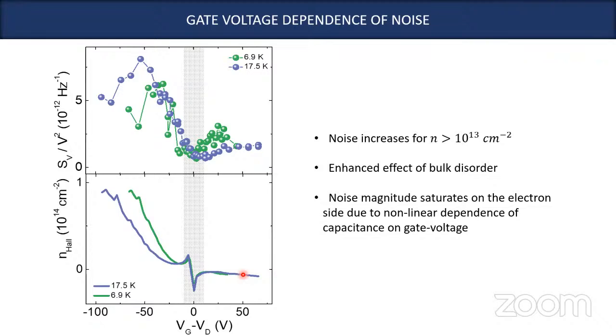You have a gray line, a broad line. That gray line corresponds to close to the Dirac point, where you have zero number density. So these are the charge neutrality points. Yes, because it is plotted as Vg minus Vd instead of Vg, so at Vg minus Vd equal to 0 is the Dirac point. We have shifted it accordingly.